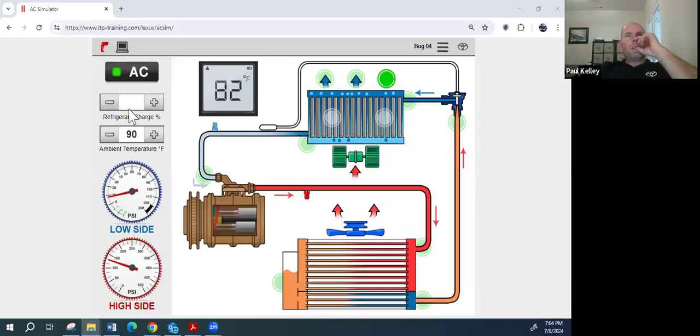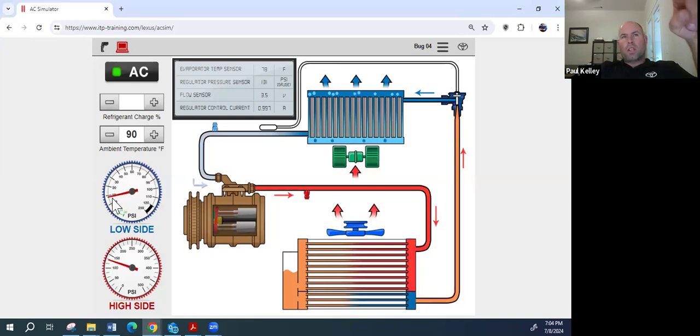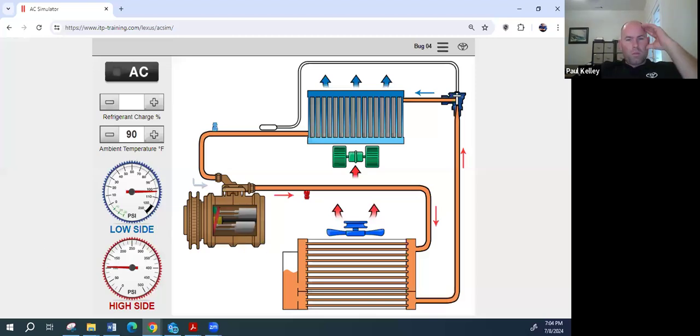Let's go ahead, turn this back off. Does it seem like at 90 degrees, based on what you've observed with that chart, does it seem like 103 PSI is going to be an undercharge? Because it seemed for a second like it could be undercharged, right? Low refrigerant level will make a low pressure. But on static, it actually looks pretty normal. So that's a little tricky, huh? What other things can we check? Anybody else got any ideas?